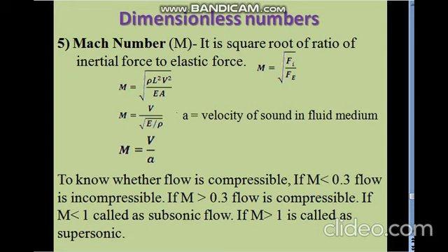What is the use of this Mach number? The use of the Mach number is to see whether compressible effects are there in the fluid. Normally, the flow of air in mechanical engineering applications is not compressible, like flow of air in an AC duct. Flow of air over a car is also not compressible.